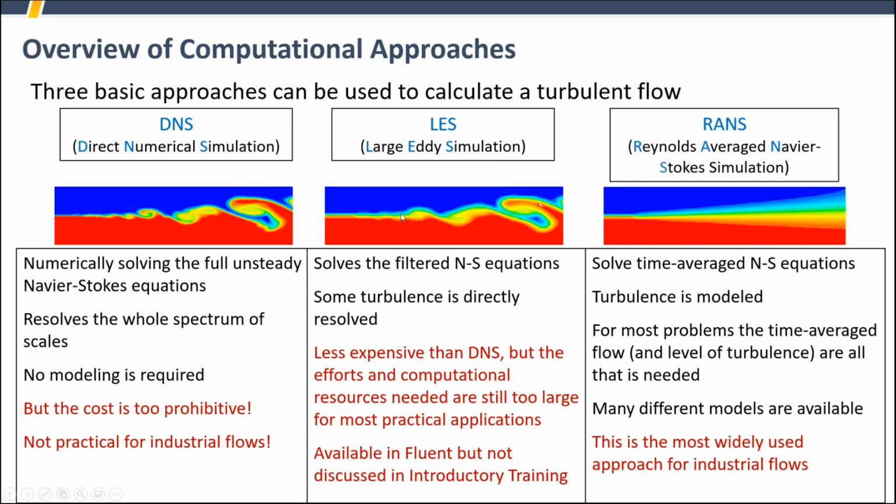And that's really important because if you're picking up small length scales, say you've got a vortex that is a few microns across, you want to have at least 10 mesh elements across that vortex, because that's going to help you pick up the swirling flow. If you don't have multiple mesh elements across that vortex, you're not picking up the swirl. You're having some averaged velocity in one single given direction.